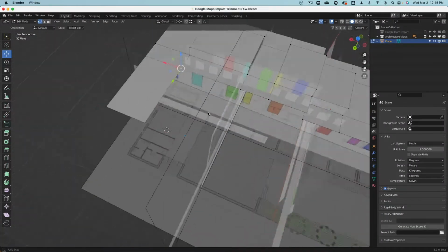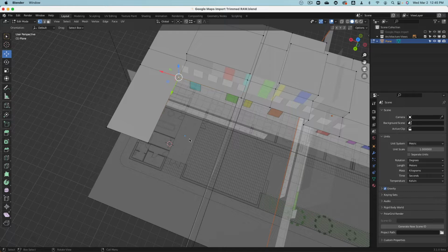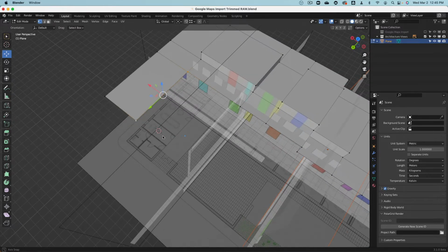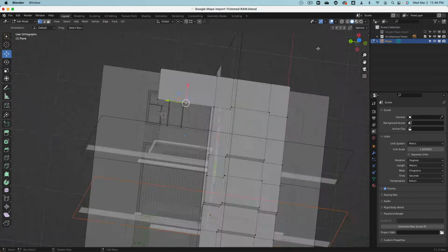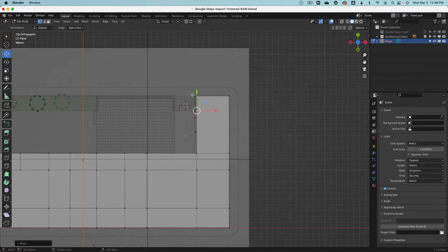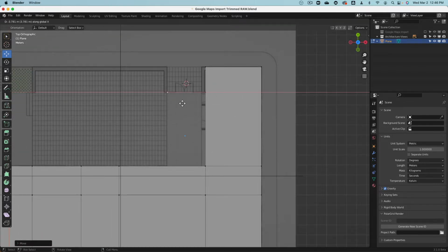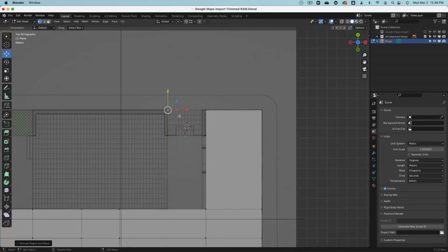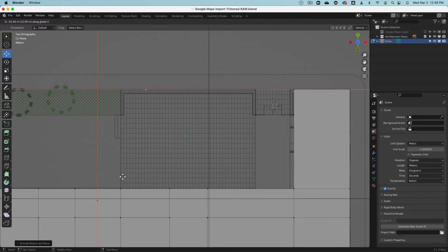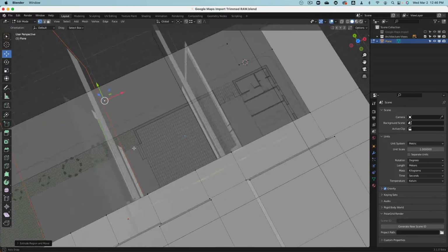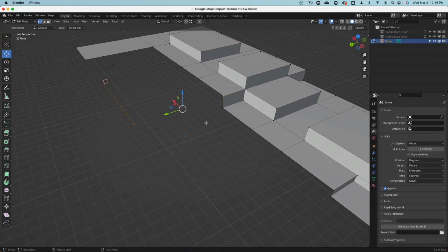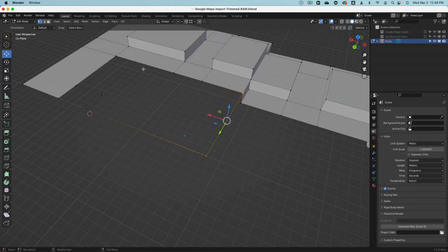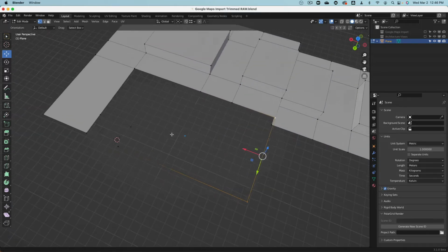Okay, so how do we build this? Again, we want to have some sort of a thing that goes in there. So this edge I need to subdivide. So I then can go into a top view. This point has to move to there. Very good. And then E and X, this goes over to here. And then E and Y, hold control, go to there. E and X, hold control, it goes to there. And then you see if we put this in, this should be kind of like a nice flat layout.